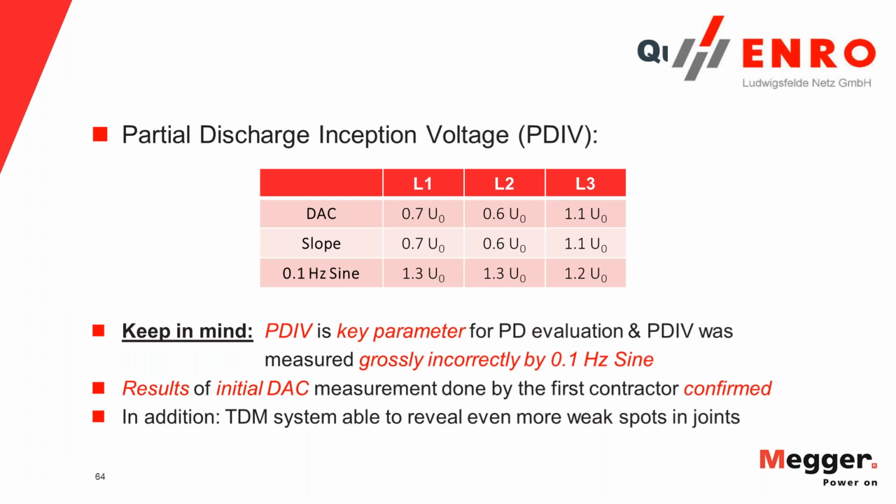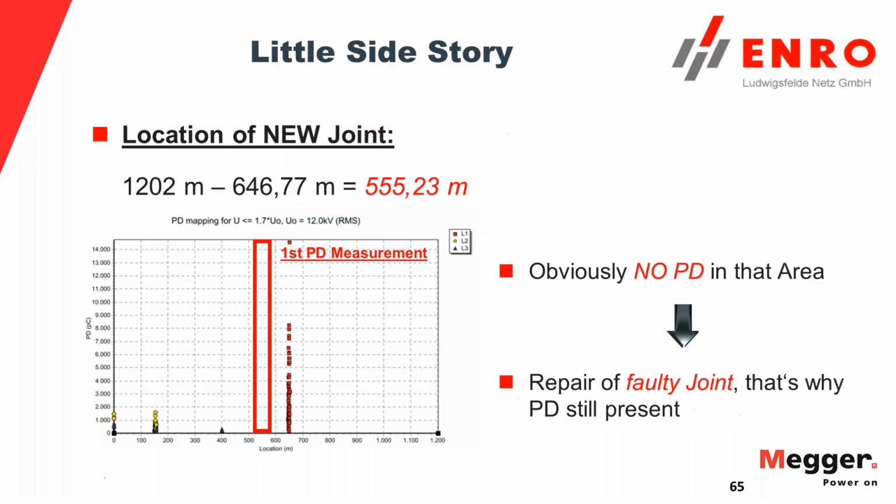You would have walked away and you would have said, yeah, there's something going on, maybe inception here at 1.3. I come back in a few years or something, whatever your risk management is. You elevated it probably from green to yellow, so you monitor it closely, but you're not in an alarmed state. Like you don't say, oh, this is a critical condition. While the other two waveforms tell you there is failure imminent, and you have substantial problems in the splices.